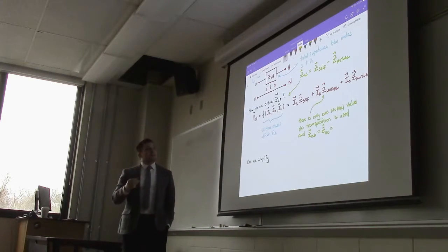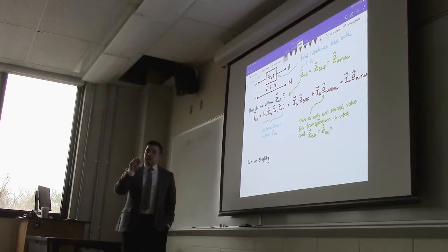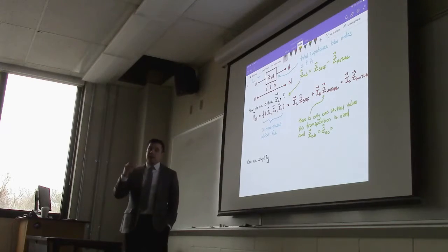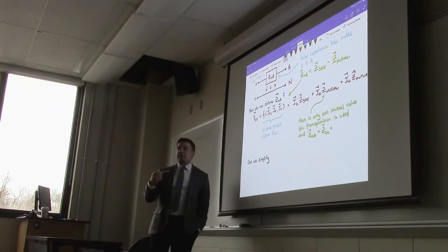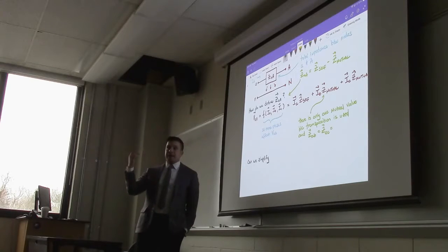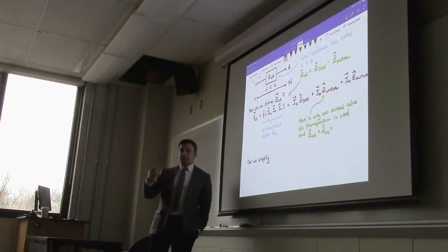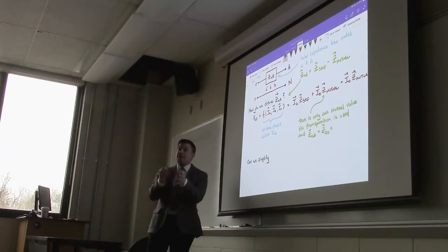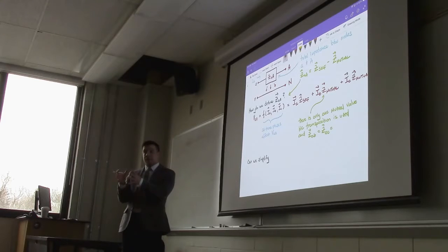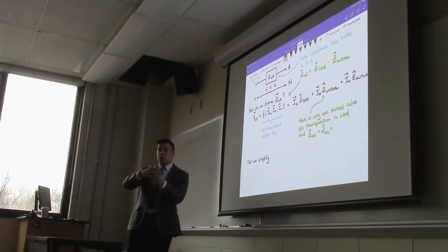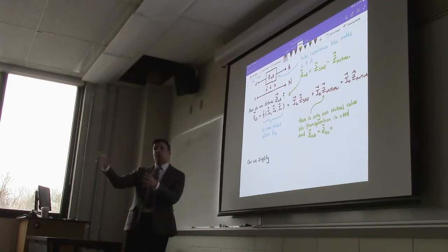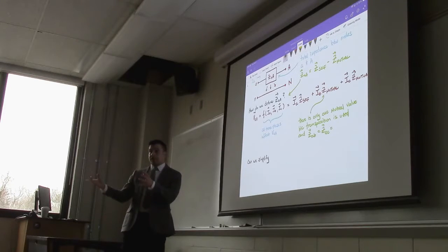Now, when you have an inductor, it creates a magnetic field, and let's say 70% of that magnetic field is contained to that actual inductor that's on that line. That's the self-inductance. A certain percentage of that magnetic field, or the power associated with that magnetic field, is going to be transmitted to another one of the phases. It's going to reach another one of the phases. That's the mutual inductance that we're talking about.